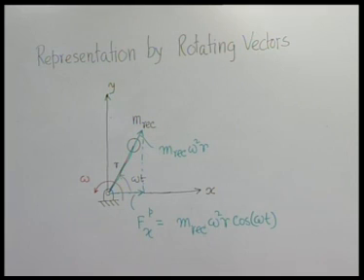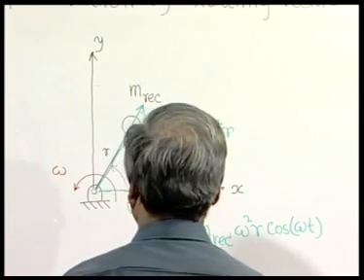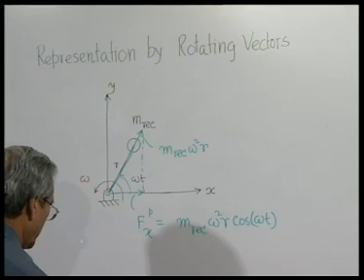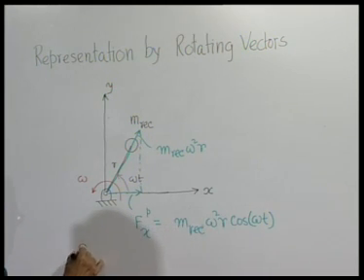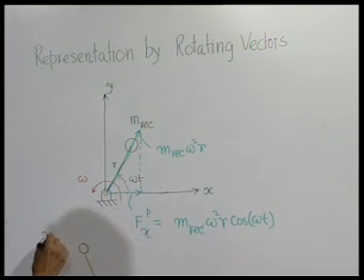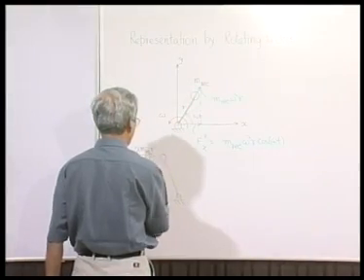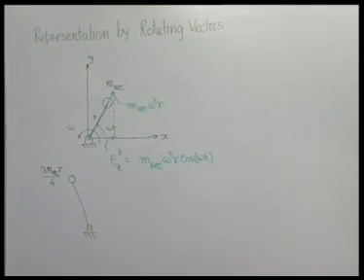Now, if this is the primary component of the unbalanced force produced in the system, what about the secondary? To represent the secondary one, we use another crank and we keep the mass which is lambda m reciprocating by 4, not r, sorry, at an r distance.